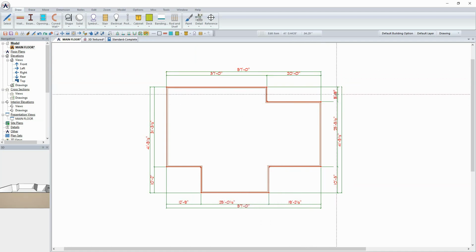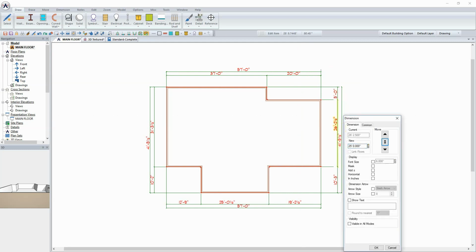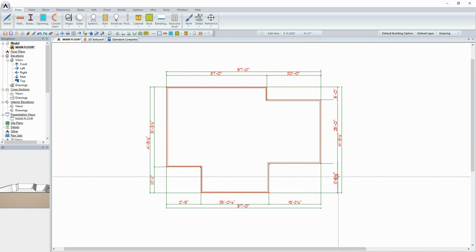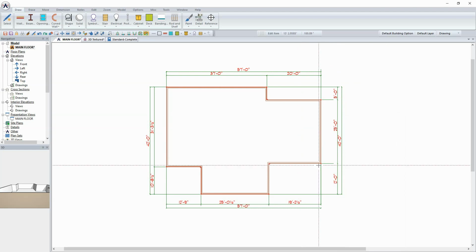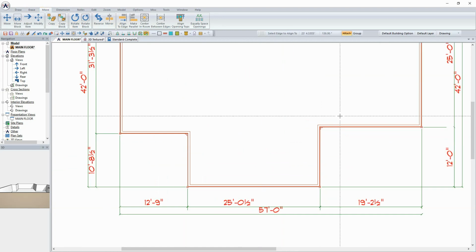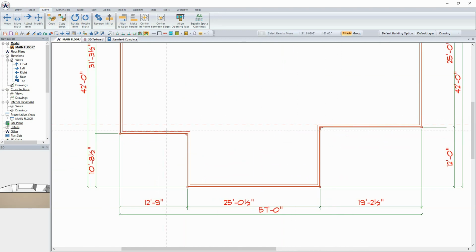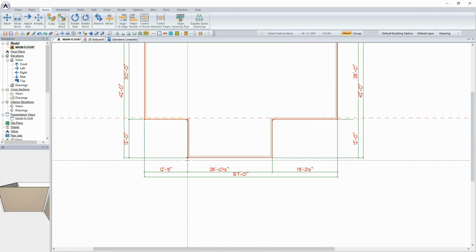Now moving top to bottom, I'm just going to continue to modify the dimensions as I see fit. Remember, this is the existing structure, so we are simply modifying these dimensions to accommodate the change. Now, a tool that could be helpful here is we know this wall and this wall are supposed to align, so rather than editing the dimension, I could come in through move, and in this case align to edge, and I'll zoom this up, and I'm going to click the inside of the stud here and the inside of the stud there. It will adjust the dimensions to suit automatically on the plan.